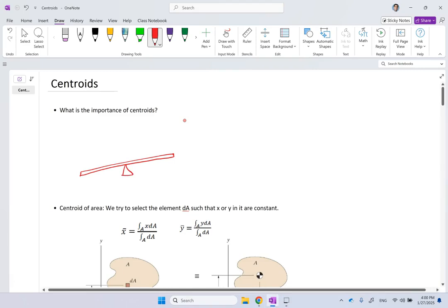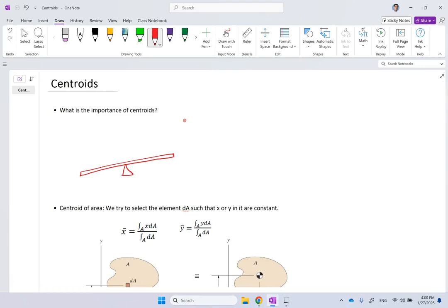And then if these two people, assuming that this is exactly in the middle of it, right? If these two people that are sitting here have the same weight, of course, it is going to be balanced, and this bar or beam is going to be flat or horizontal. If one of them is heavier, then the center of mass of these two objects and the beam will move a little bit to the left of the support point. So the centroid is going to be here, and that centroid will create a moment about the support point O, and that will cause the rotation.